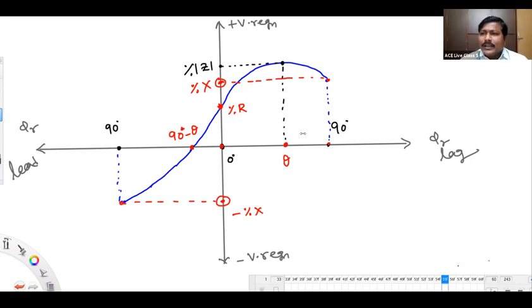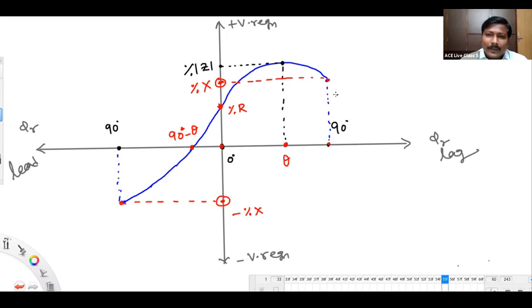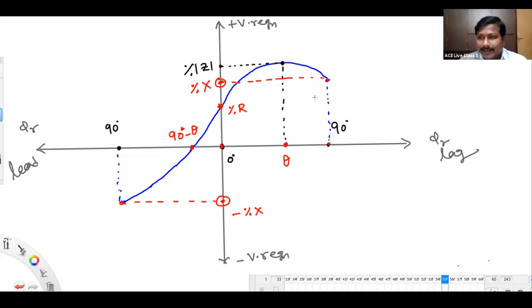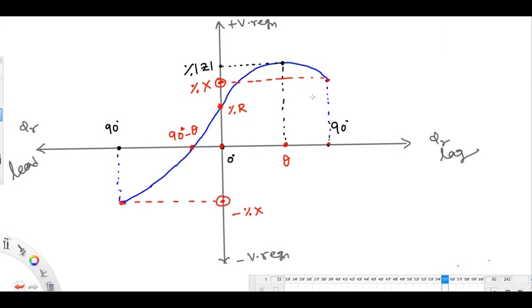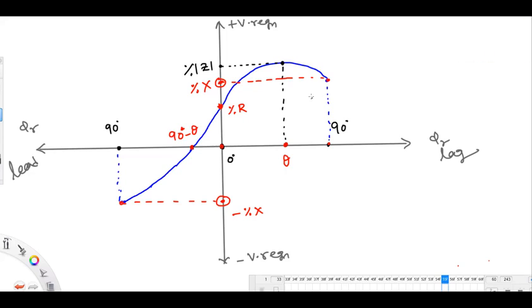See, star grounded or star ungrounded will be decided by your nearby winding. Is it a generator nearby or a transformer nearby? If that winding neutral is grounded, I will say it's a 3 line, but neutral is provided by ground. Okay, sir. There is also 3 phase 4 wire. Yes, sir. But the 4th wire we are not running. It is taken as ground. Okay, sir. But in case of secondary distribution, especially, we are running the neutral wire, for load purposes. Okay.